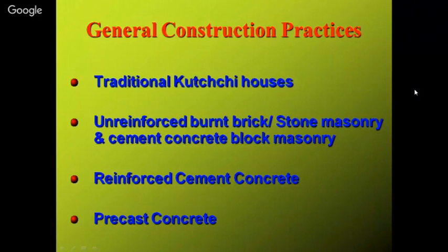For those who are not civil engineers, there are two types of construction. In one, we make beams and columns, and in the other, which is how we make our own houses, we keep the walls and on the walls we have our roof. That is called load bearing type of construction. For load bearing construction, we recommend 3 to 4 story buildings, but in case of framed structure, you can go up to any height by proper design and proper planning.